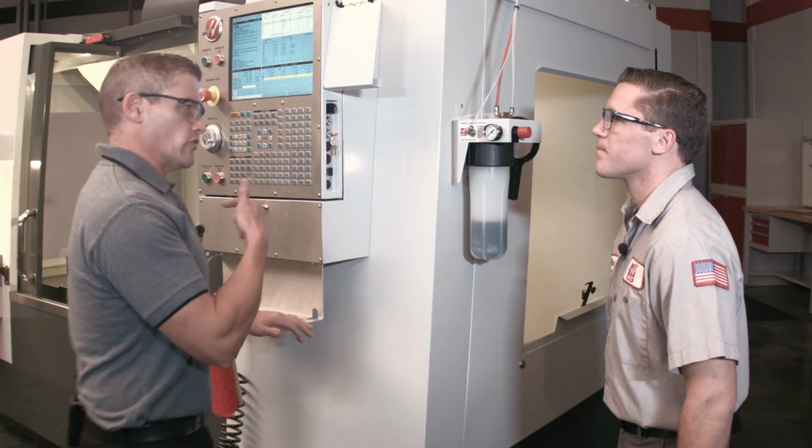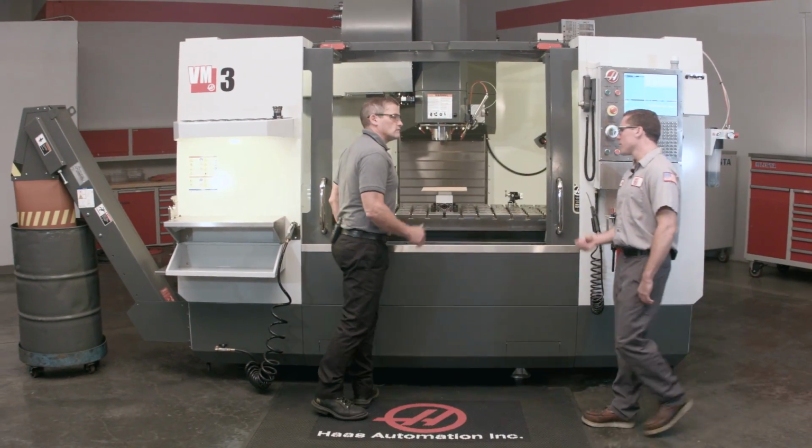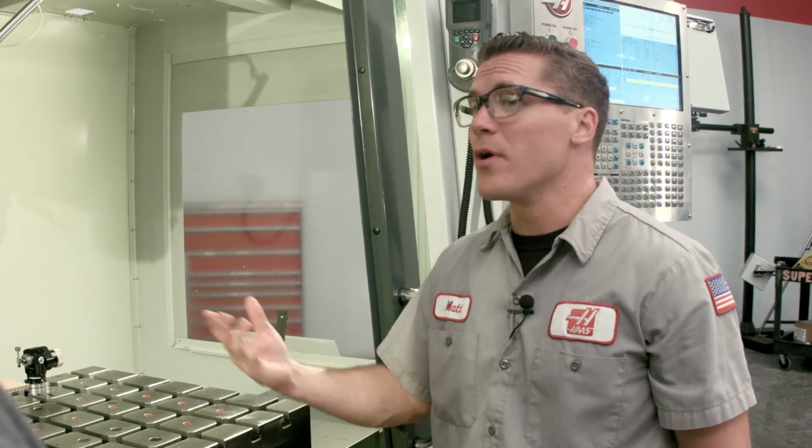Sounds good. Let's head back to the front of the machine. All right. So how much of that oil are we actually using? We're using about half an ounce of oil per hour of cutting. This is pretty typical of an MQL application, and some run even leaner than this. Wow, that's not much oil.